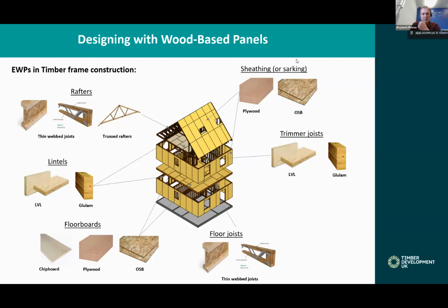Floor joists: most commonly, engineered wood products used for these applications include thin web joists. And wall studs. There are also ways of using thin web joists as wall studs. This is actually a very efficient way of increasing the insulation of the wall.